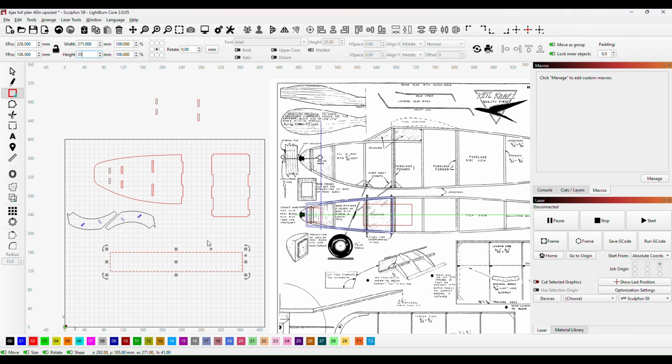and then what I'll do is I'll then just put that onto our shape here, or onto our main plan, and if we have a look at that, it's just touching the bottom longeron there, and it's touching the bottom longeron just there. So I think that will be fine, and we'll probably need to cut this former, and this former, so that the battery can sit somewhere around there.